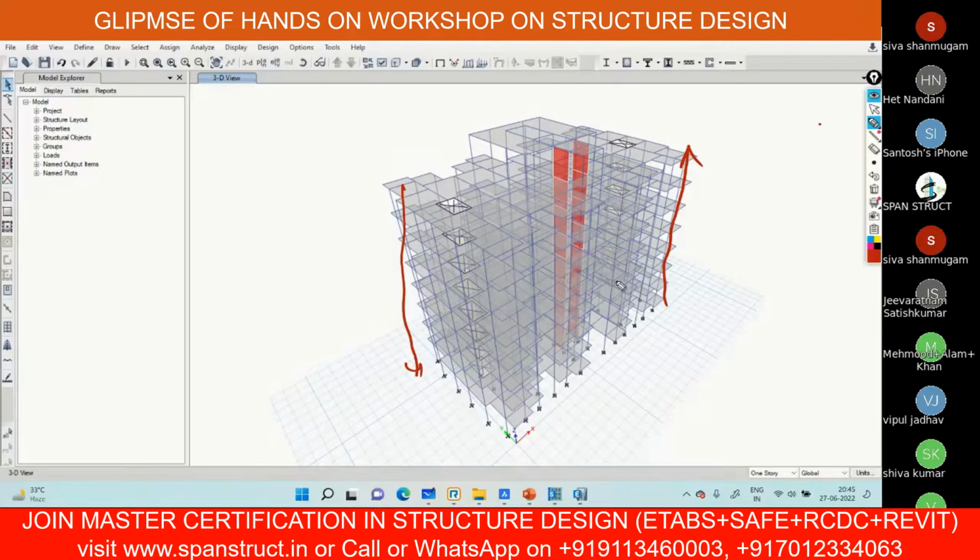This also is not to be done for every structure. It is for structures which have floating columns, deep beams, spandrel designs and so on, tall structures and all. In that case, you may perform this construction sequence analysis. What is a spandrel? A spandrel is actually a deep beam. You may call it a spandrel deep beam.